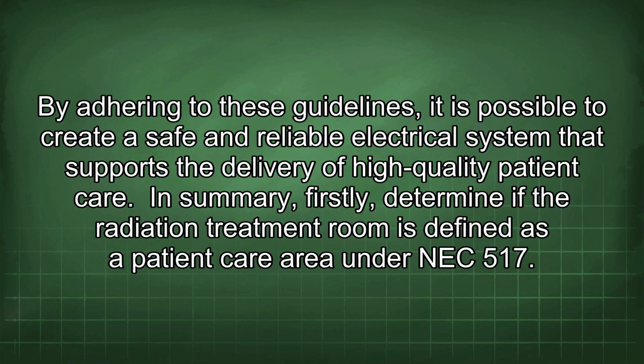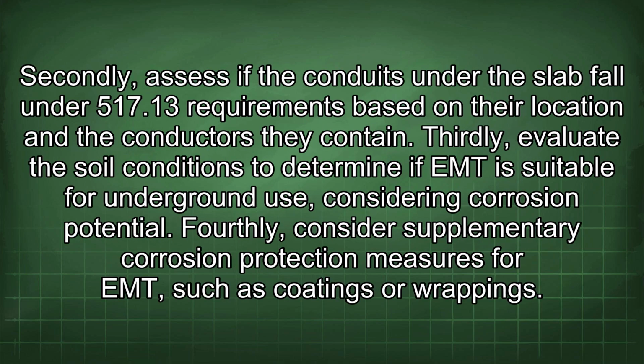By adhering to these guidelines, it is possible to create a safe and reliable electrical system that supports the delivery of high-quality patient care. In summary, firstly, determine if the radiation treatment room is defined as a patient care area under NEC 517. Secondly, assess if the conduits under the slab fall under 517.13 requirements based on their location and the conductors they contain.